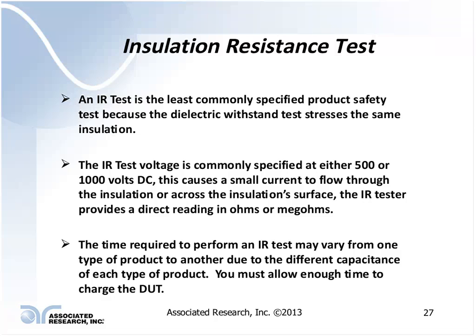It's also done normally always using DC, again 500 to 1,000 volt potential, where most withstand tests are normally specified as an AC test potential. If you do a DC test, it's usually done at the peak value of whatever the RMS test potential actually is.